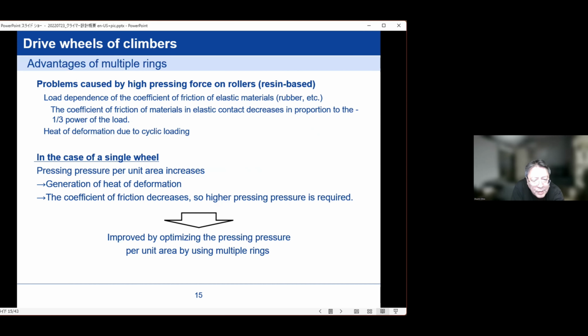experiments at actual speeds. If you don't know the coefficient of friction between the material of your climber's wheels and the tether, then as shown in the picture below, you can use the tether material and the handrail, and weights, and pull them with a bar, and then you can conduct an experiment to measure the coefficient of friction.